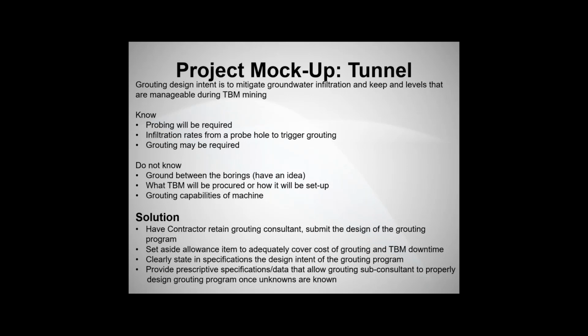One of the big things with grouting specs is that you've got to be clear in what the intent of the program is and what you're trying to do. If you're not clear, well, then the contractor isn't going to be clear, and there's going to be question, and you're going to get answers or an increased cost. But then what you can do is provide prescriptive specifications, and because you've already gone through design, you've got all the grouting information, all the grouting data, that the grouting contractor needs to allow them to adequately design and submit the grouting program once all of the unknowns are now known.